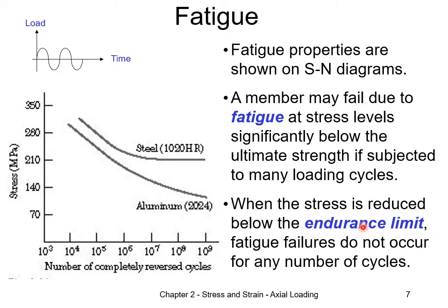If the repeated cycles of stress are all below this endurance limit, fatigue will not occur, regardless of the number of cycles. This is like taking your paper clip and then repeatedly bending it. If you exert small deformations in the bending cycles, the paper clip will hold in place. But if you exert more deformation in the bending cycles, the paper clip will undergo fatigue and break off.